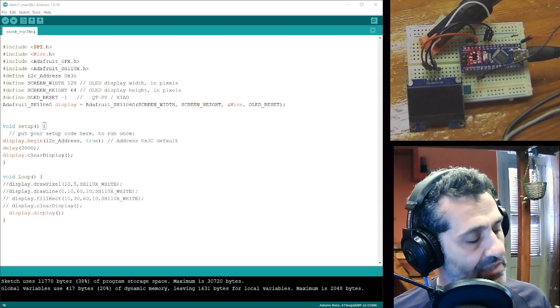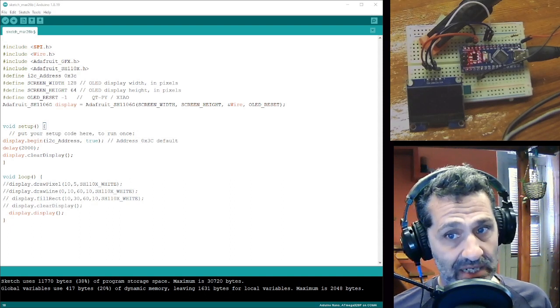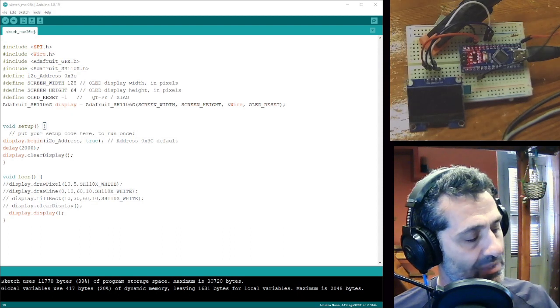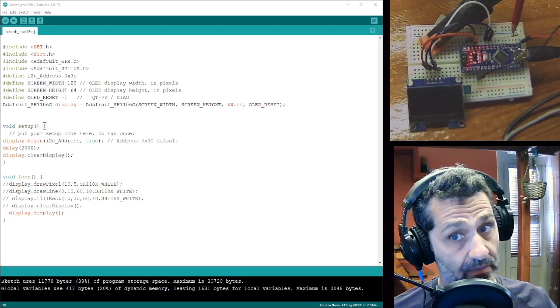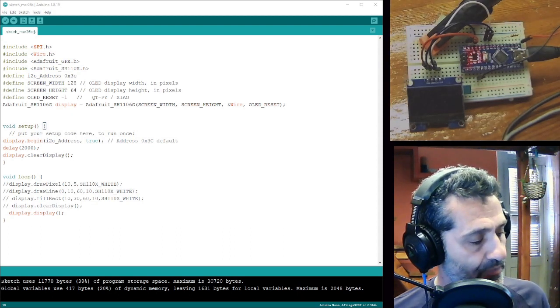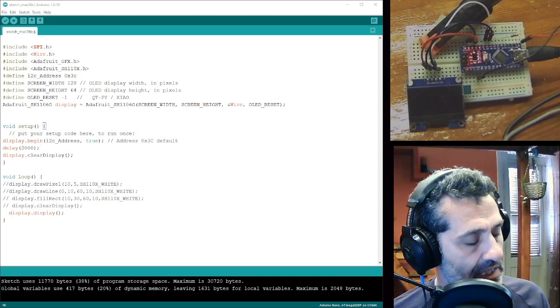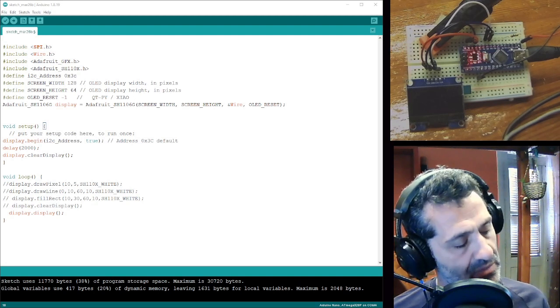So I would leave it as it is, but I have a 1K resistor in series with the signal, and the only purpose of this resistor is to block negative values from introducing too much current.